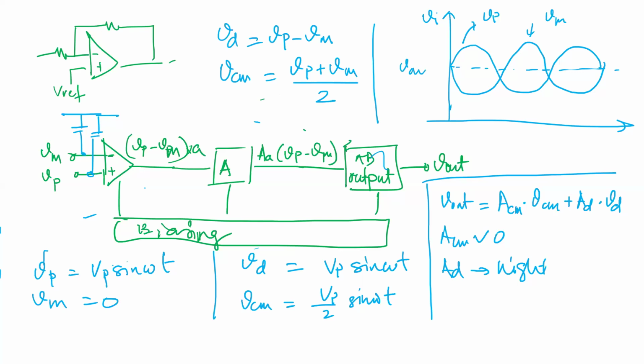You got it? So basically that VCM will be this noise signal. If you didn't have this quantity at 0, then the output will be your signal, and your noise also will be amplified. So that's the other reason people use differential amplifiers: if you have a noisy environment and you're carrying the two wires lengthwise, then you cancel those noises as well. Clear? So that's the basic architecture of an op-amp and why you need differential gain, and the common mode gain to be 0, because that's what is required for your op-amp circuits.